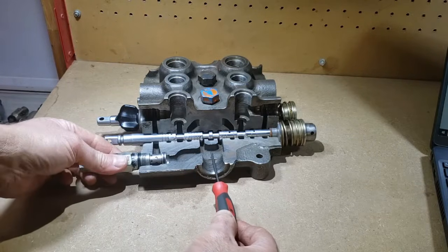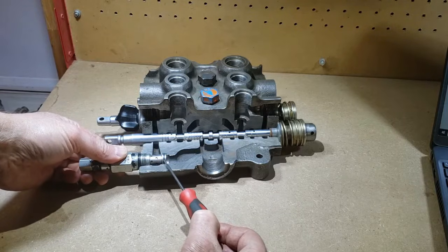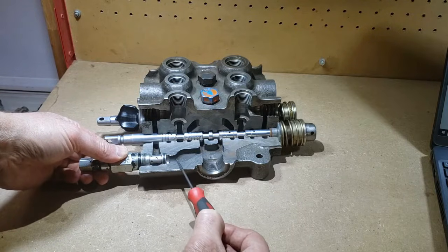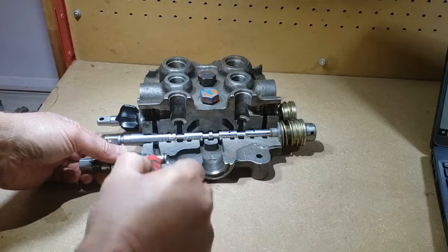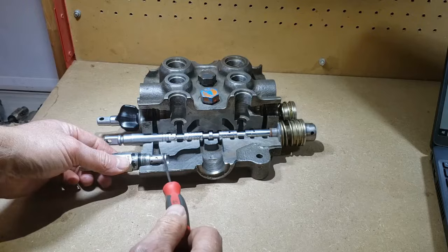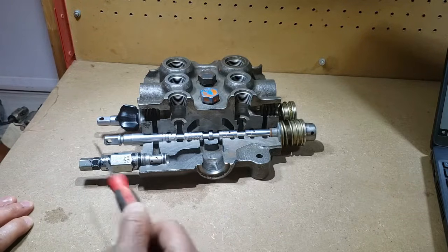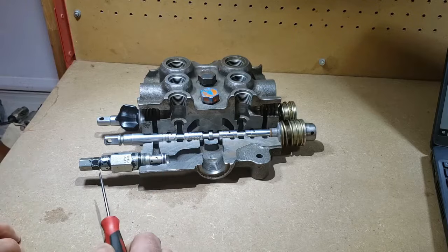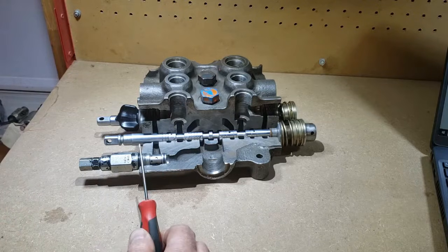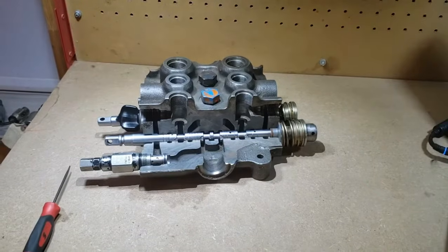And then the main relief valve is a cartridge type threaded in here. Very important seal here on the cartridge valve, keeping high pressure from this passage here, which ends up going back to tank. So the relief valve is going to stay closed, but if there's a pressure spike over the setting, I believe it's 3,300 on this particular reference, then it can open that relief.